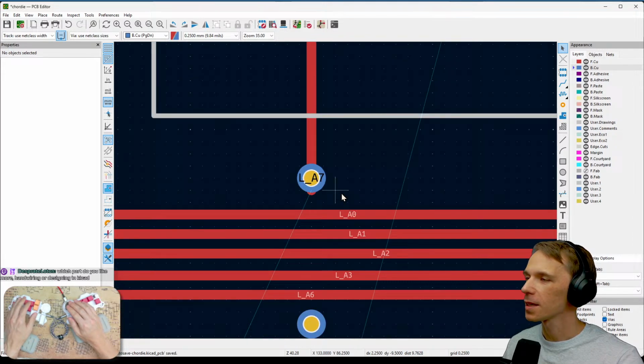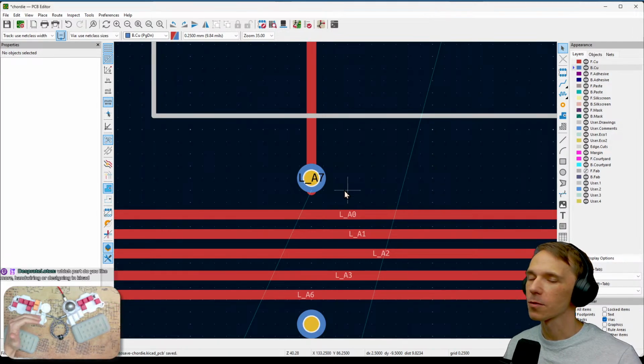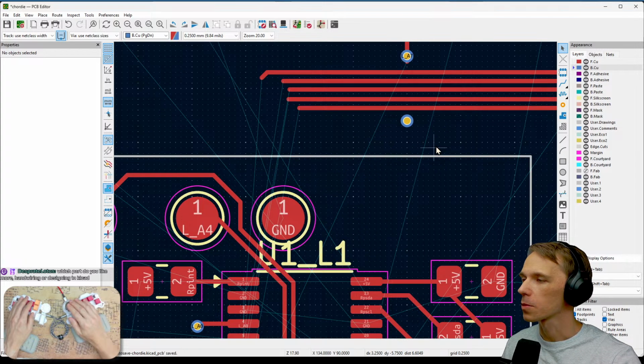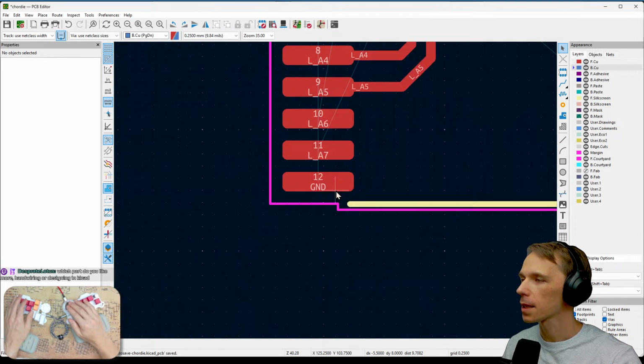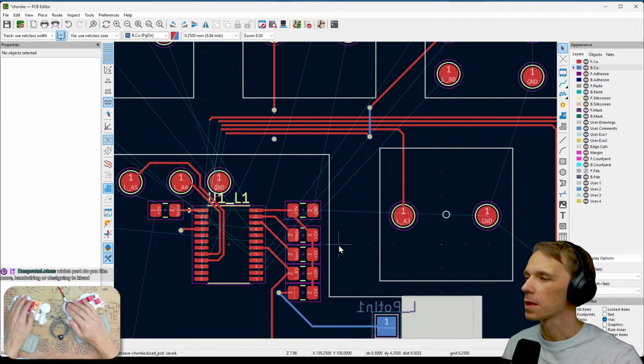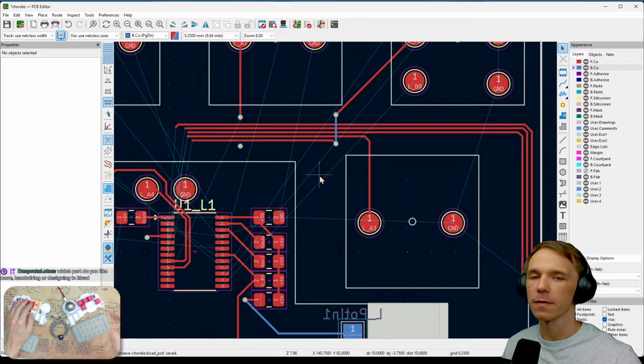If you're making a PCB, it's always an issue because the vias are too close, then the tracks are too close, then some tracks you have to, like over here, so we have to connect tracks like A7, A6 and so forth, but the order they will be coming in will be reversed, so then we have to do some swapping.